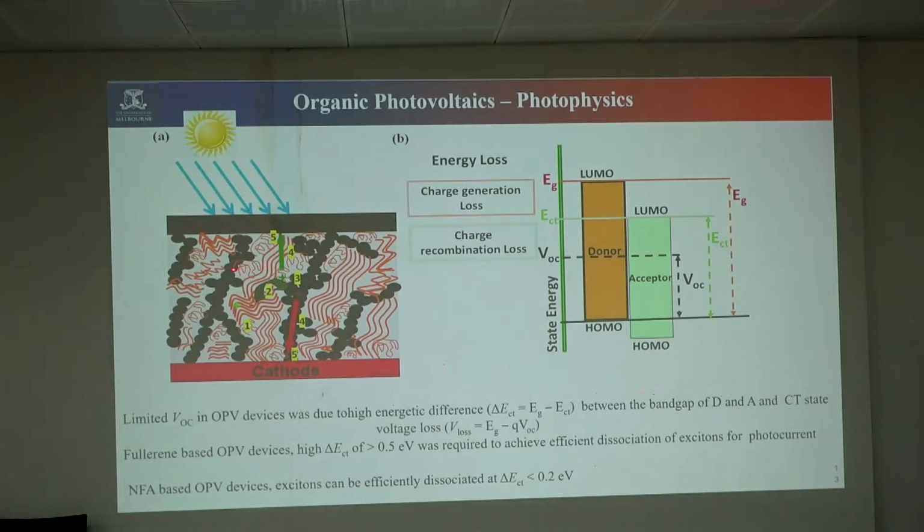But we can't expect that the holes only travel this way. It can travel this way, it can travel anywhere. If it travels this way, the holes will encounter recombination here. If luckily it travels this way, then it will get extracted. So we can't expect where it's moving. And also, most of the charges travel this way. Why? Because